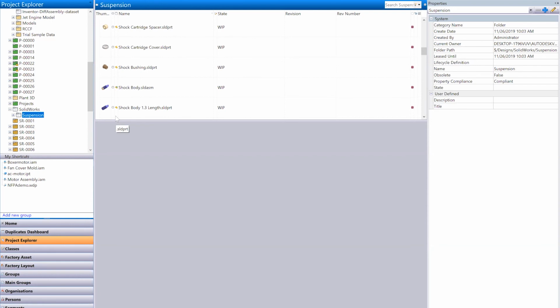Don't do it. That checkbox, that check design files, is there for that very reason. Other types of files that don't have file relationships, so things like Word files, Excel files, movies, pictures, that type of thing, perfectly fine to drag and drop into the Vault. But CAD files, you want to use the add-in and the check-in tool to do that, or the Autoloader, or the other various ways that Jose outlined today.